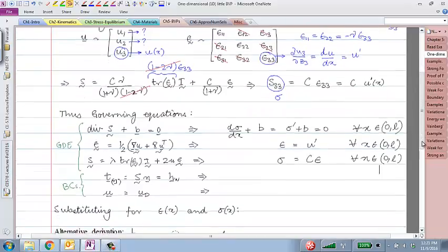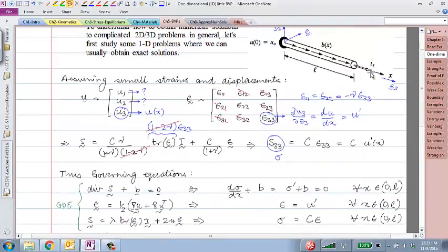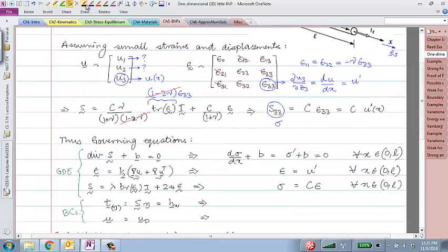So that gives me traction T at L, T sub L. Traction T sub L is equal to sigma acting on plus 1. That's just the one-dimensional equivalent of the Cauchy stress traction relationship. Okay. On the left face, U at 0 is equal to some specified displacement.